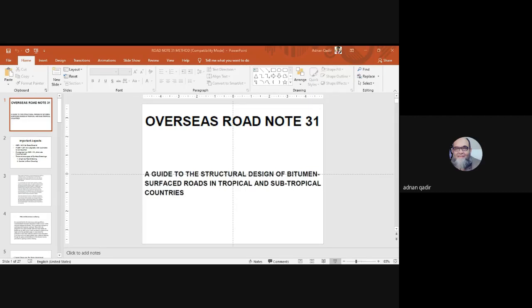Then there is another type of surfacing, that is a flexible bituminous surfacing. You can call this flexible asphalt surfacing as well. So it is essential that a thin bituminous surfacing of 50 mm, which is what we call asphalt, is generally recommended for the structures described in charts 3, 4 and 7 of the structural catalog, which are flexible. This is particularly important for surfacing laid on a granular road base.